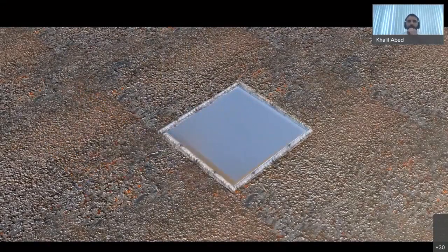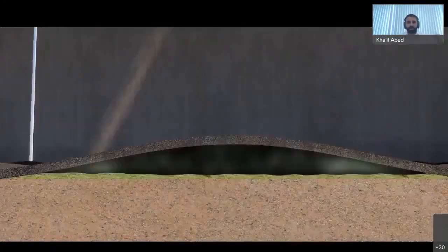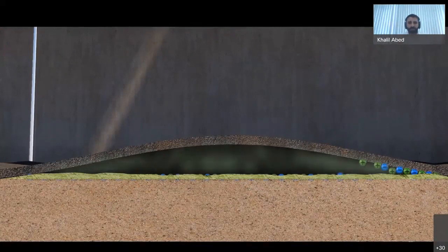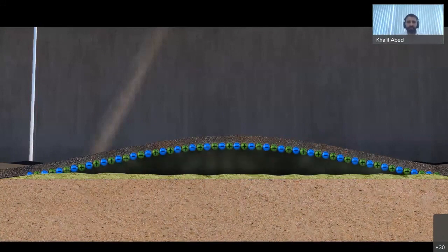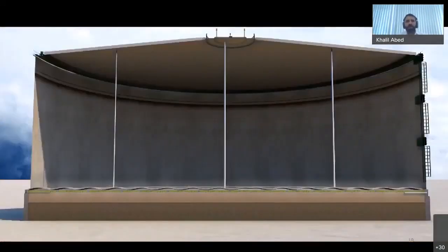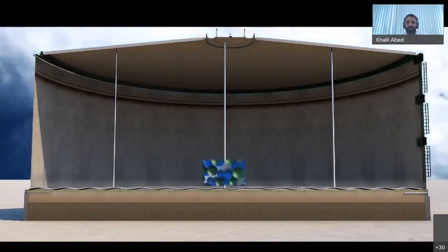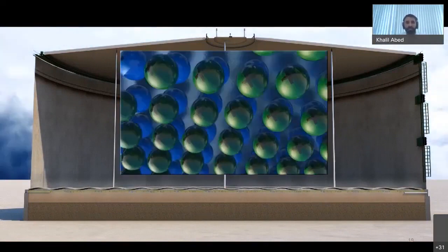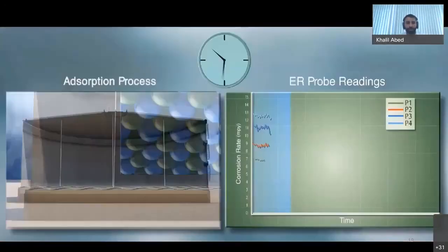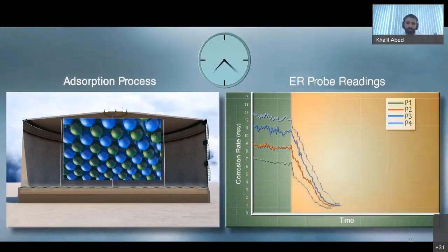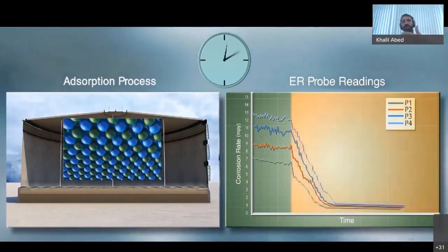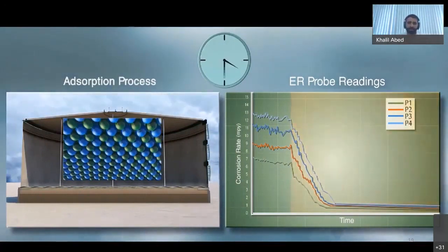the hole, and then once the powder is trapped under the tank floor, it starts to sublimate, and then it releases the protective molecules and provides the protection against soil side corrosion and suppresses the active corrosion rate on the tank floor. And with the use of the corrosion monitoring probes, you can see the effect and the reduction in the corrosion rate with time.